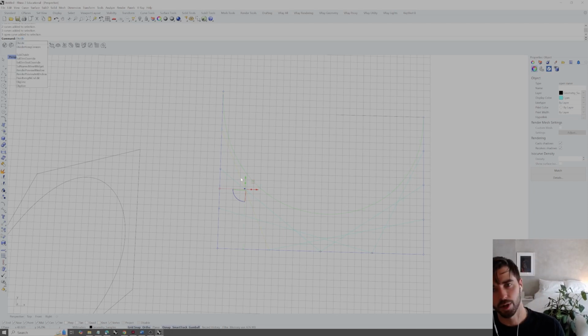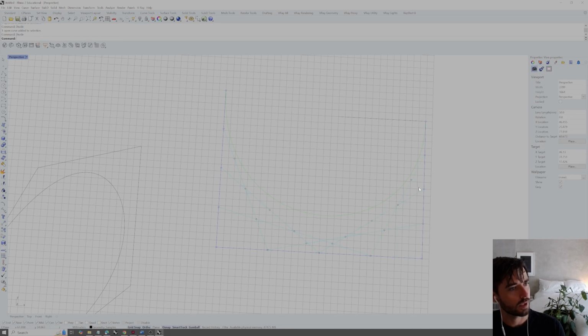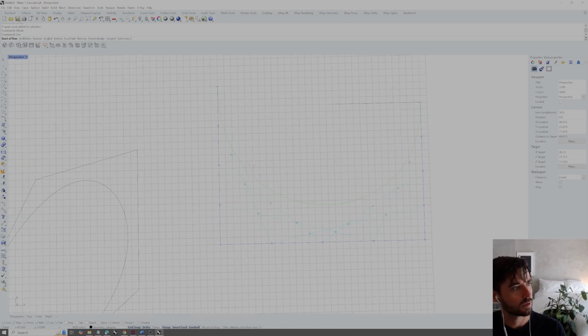So we'll go through another round of dividing each one of these curves. So divide, divide, divide, divide, divide, divide. And we're going to do the same thing on these 2 to 3 connections. So we now have each one of those divided. So now when we draw this additional line, which is the third degree, which should be tangent to our green NURBS curve here, what we're going to do is take the index relative to which index curve it is.